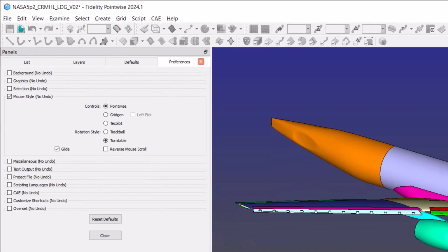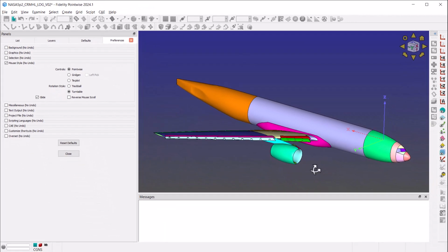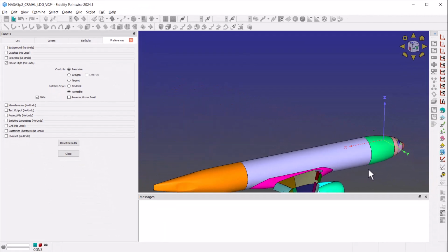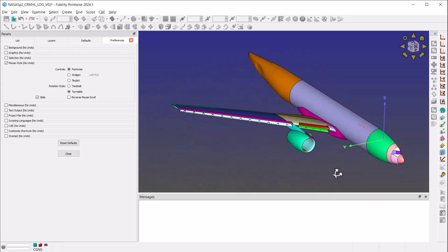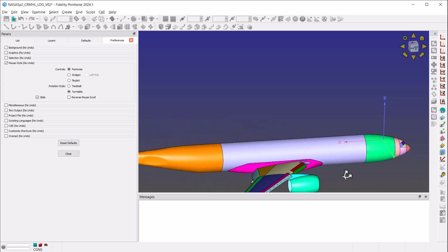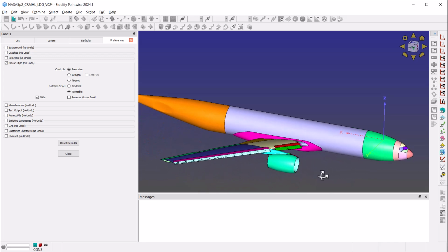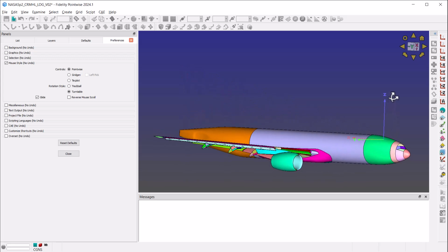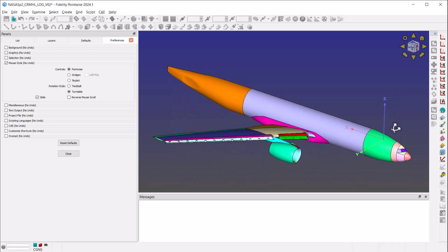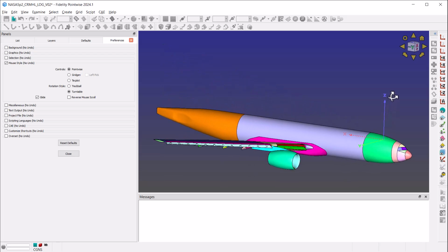With this option, you can rotate the view about the rotation point, but the rotation will be performed about the currently vertical rotation axis. In this case, it would be about the z-axis. But you still get to tilt the vertical rotation axis forward or backward, but not sideways.